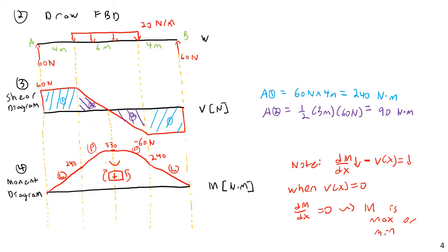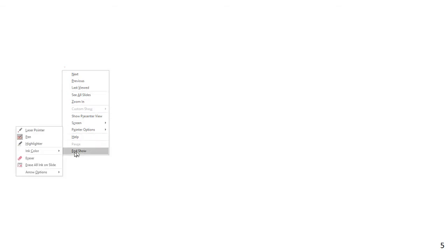Maybe I can look at a cantilever beam, and we can see. If you really want to see the difference, I would encourage you to solve through these also using the method of sections or the method of integration, to really compare how different and how quick the method of inspection can be once you've got the hang of it.